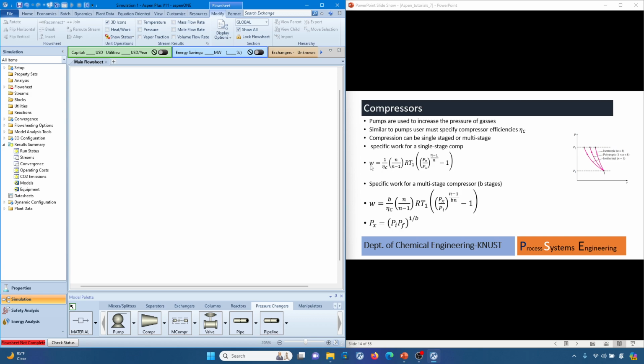There are multi-stage compressors used to curb this, by compressing in stages when the desired pressure ratio is high, for instance pumping from 1 to 40 bar or 2 to 80 bar. They reduce the work by keeping the temperature constant, achieved by cooling and removing the heat associated with compression for every single stage.